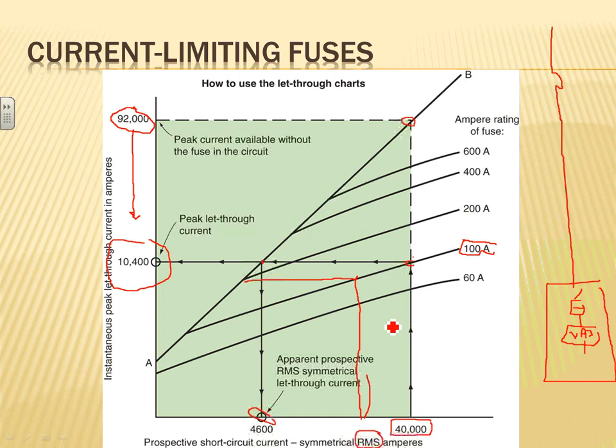In cases where there's a very high fault current, your typical utilization equipment is rated at 5,000 amps. So if you got 4,600 through, it's fine. But if you didn't count on that fuse, or you didn't follow Mr. Brumlich's guidance and some other value let through more than 5,000 during a fault, that's a problem.